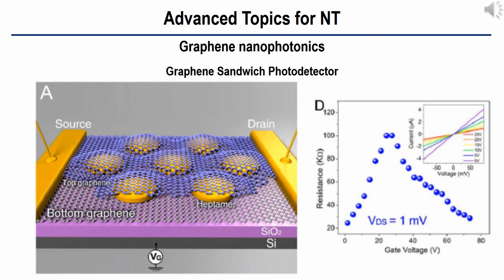There are problems for graphene photodetectors, such as low light absorption, difficulty of extracting photoelectrons, and absence of photocurrent for uniform illumination. The voltage current produced in two terminals will be of opposite polarity. To solve these problems, one can use plasmonic nanostructures near contacts, where incident light is converted to plasmonic oscillation by enhancing the local electric field.